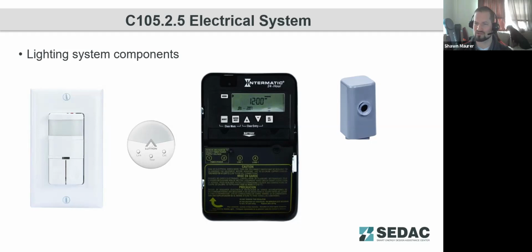You're going to be spot checking controls, making sure they're connected to the proper bank of lights and that they've been properly wired up. I was commissioning a building as a retro commissioning agent, and they had the controls to the lighting switches wired up in reverse. So a lighting command from the BAS, the building automation system, to turn the lights on would actually turn them off. And that did create some confusion in the operation of the building and setting up schedules and things. And so it's just going through and verifying through a commissioning check that things are properly set up, that they're going to work with the proper commands.